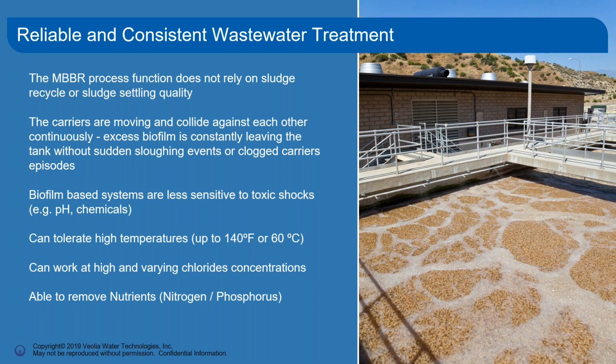The carriers are moving, colliding with each other and cleaning each other, and the excess biomass will leave the tank, and you separate it after the tank to have clean water going out. Experience is that biofilm-based systems, such as MBBR, are much less sensitive to toxic shocks. So you can have spills and things, and it will take it well or recover very quickly.